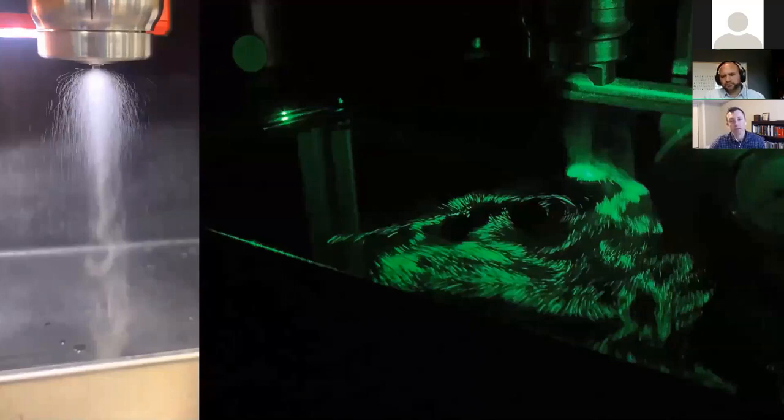Usually the liquid mass flow is not something that we independently determine. Unless, for example, we can't achieve good atomization, we might need to then use, say, two nozzles or more nozzles to pre-distribute the material through multiple nozzles or across a header.